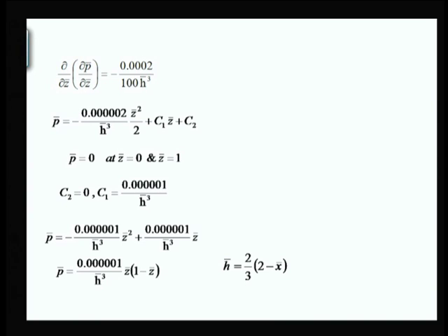Now, film thickness is already known, that is in terms of x bar, and I mentioned clearly that this is a better pressure profile compared to the previous one, because this is also expressing pressure in terms of x bar. It is not only z bar, it is also expressing in terms of x bar. So, it is giving a two dimensional profile.